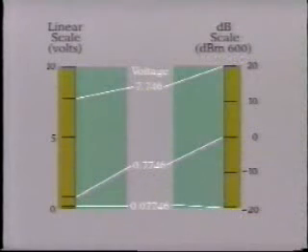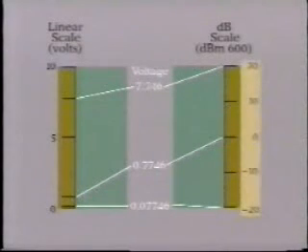Let's briefly review the principle of dB measurement, which has a corresponding power level at a specified resistance value. Note that the dB scale consists of plus and minus levels. Conventionally, the 0 dB point is defined as the specific voltage which will dissipate 1 milliwatt when connected to a 600 ohm resistor. If you calculate this out, it comes to 0.7746 volts. This is RMS value, of course.